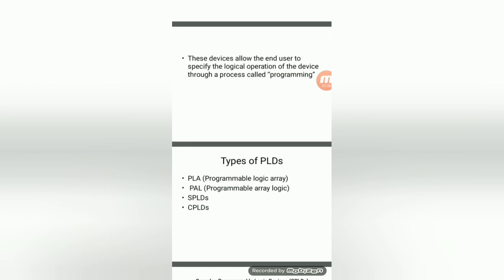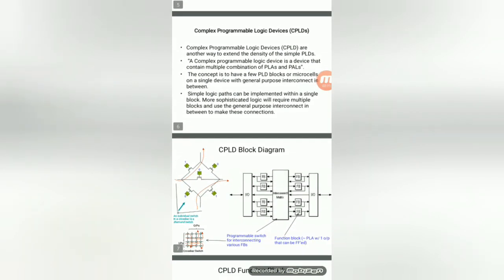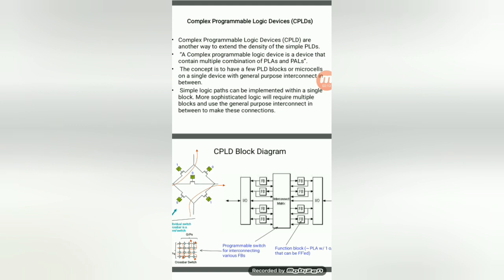CPLD is somewhat more complicated. For big or complicated designs, we can go for complex programmable logic devices. A complex programmable logic device is nothing but a combination of two or more PLDs, a device that contains multiple combinations of PALs and PLAs. The concept of CPLD is a combination of PLD blocks or microcells on a single device, in order to realize a particular function based on the interconnecting devices.